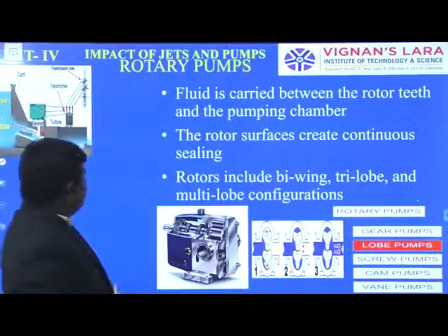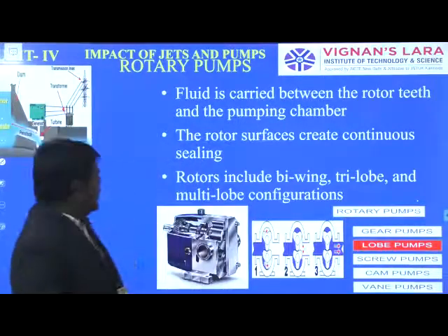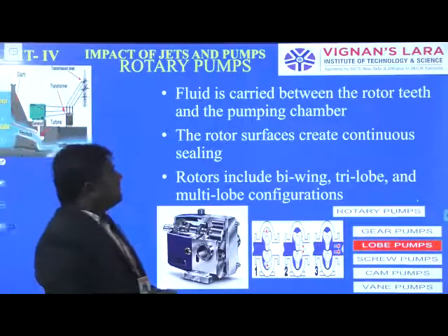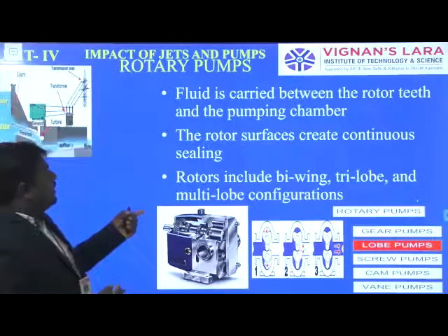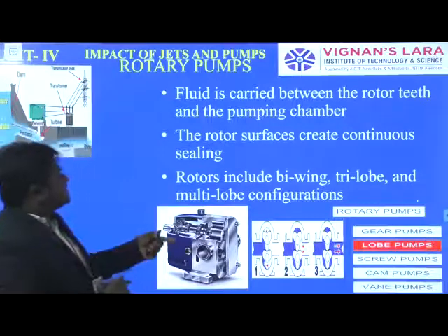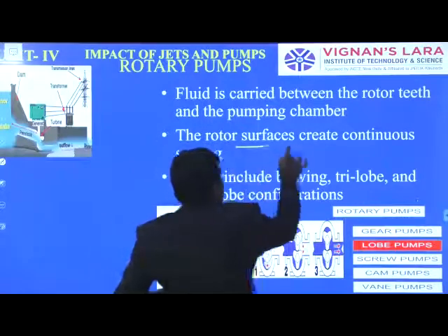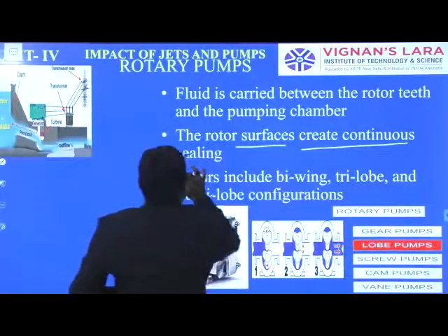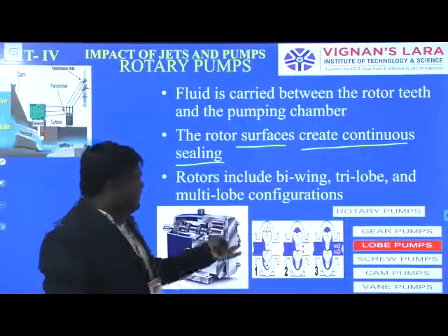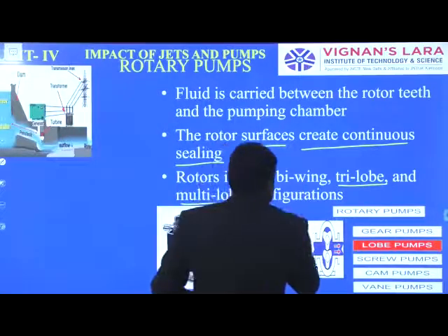And coming to the lobe pumps. In lobe pumps, the fluid is carried between the rotor teeth and the pumping chamber, and then the rotor surfaces create continuous sealing. And rotors include bi-lobe, tri-lobe and multi-lobe configurations.